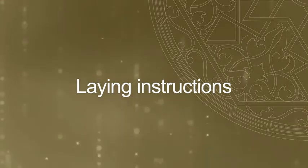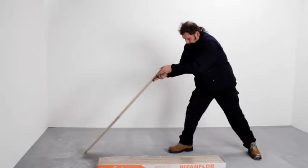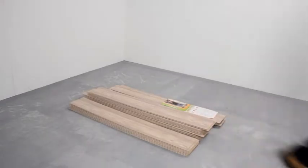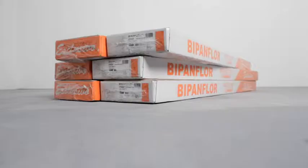Laying instructions. The floor you have bought must be brought in the rooms where it will be laid, taking care while transporting it to avoid hitting the sides in order not to damage the joints. Any break would not ensure a perfect joint. The packages must be opened and left horizontal and still for at least 2 or 3 days, so that the slats are conditioned in the room's humidity and are more stable once the floor will be laid.